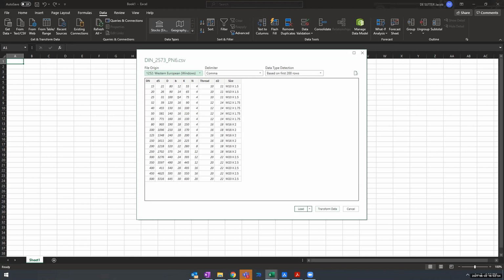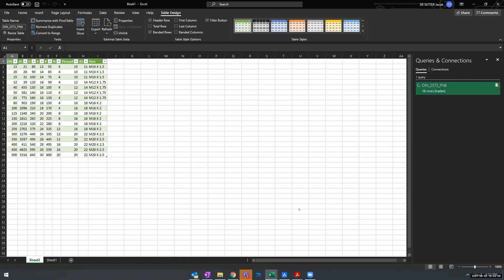And it has a bunch of columns and rows. I'll load this. Now this design table was set up so that it fits the parameter names that we used in our assembly. So you see this D5, D, BK, and all these same names that we know from our assembly. And basically, it gives you preset values for all these parameters grouped together. So this first column would be the name of your setup, and linked to this setup here are these parameter values.